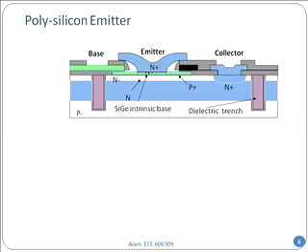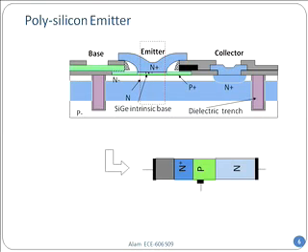Do you see how the base contact is coming through the green? And you can also see how the collector contact contacts the bottom substrate, and therefore the current flows vertically. So we will again turn it over, flip it 90 degrees and look at these characteristics. Now the hatched region that I show here is the polysilicon emitter. So now the emitter has two pieces. One piece is this darker blue, N plus, that's single crystalline, and another piece is this hatched region, that is polycrystalline material, and we will see how it works.